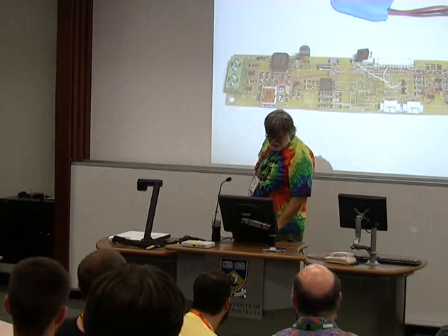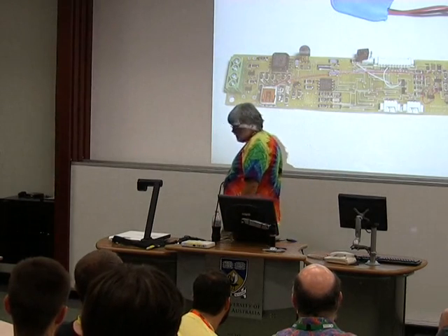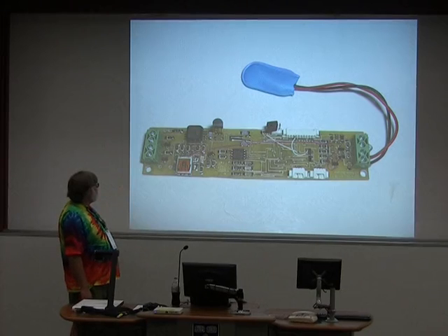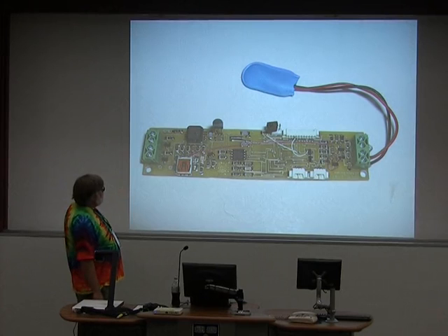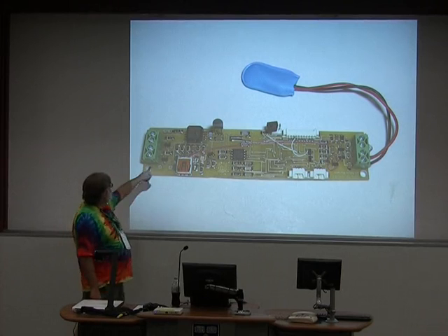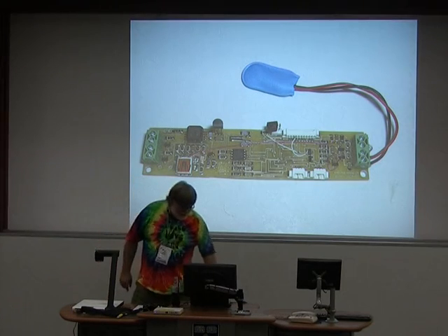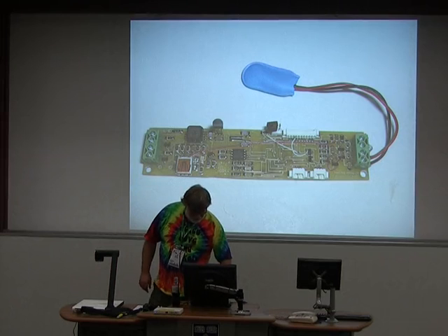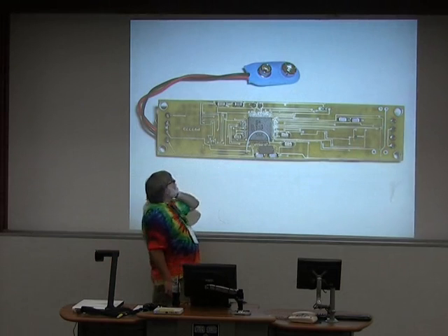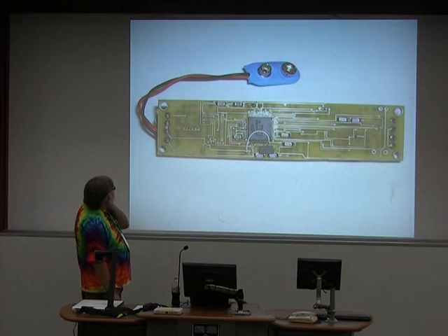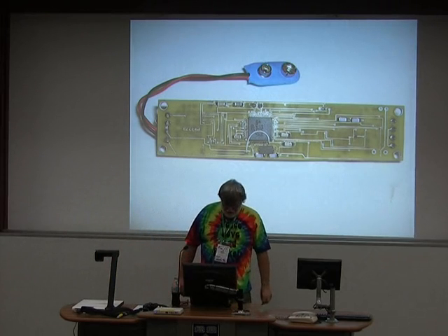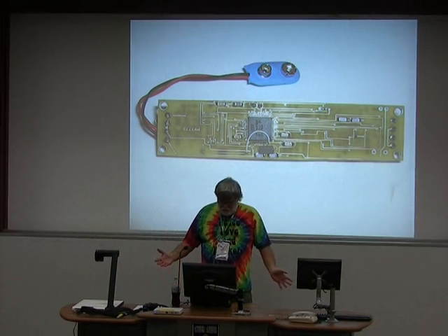And this is what that board looked like. Some of you may remember these photos, some of you this will be new for. That was the top of the board. This was done in 2 layers, really cheap circuit board fab. A hand-loaded surface mount with frickin' huge parts by my modern standards. These are 1206 passives and things you can actually see and work with without microscopes. This is the back of the board with an LPC. What the heck was it? It was an NXP ARM7 device, and that was a pretty cool board.